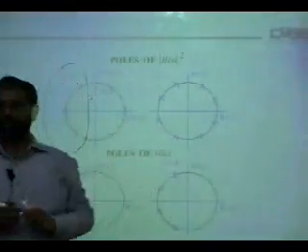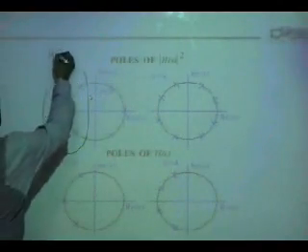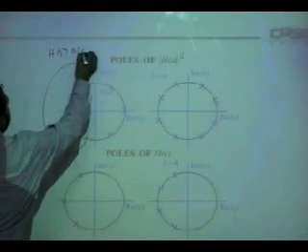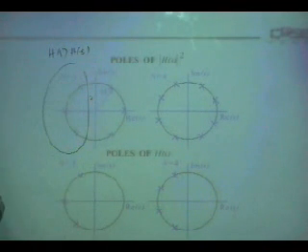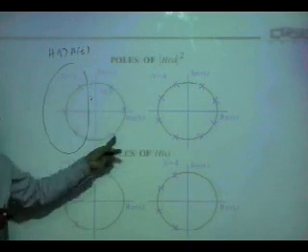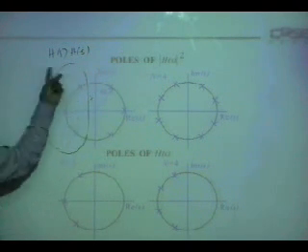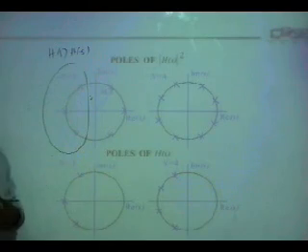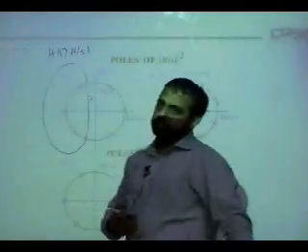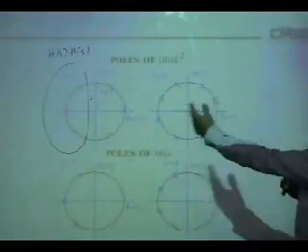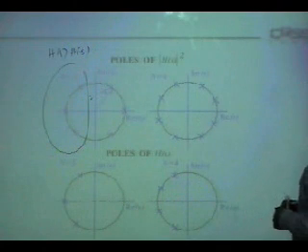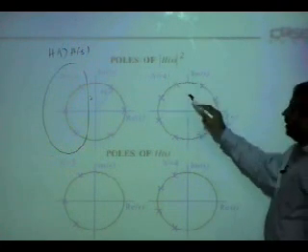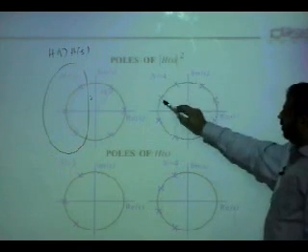Half of them should go to h of s and the other conjugate half should go to h of minus s. If I want to, I can say all these are h of s and h of minus s, it will still satisfy the equation, but the resultant system will not be stable. So you pick the ones which give you a stable system. If there are 4, then you will have 8 roots.